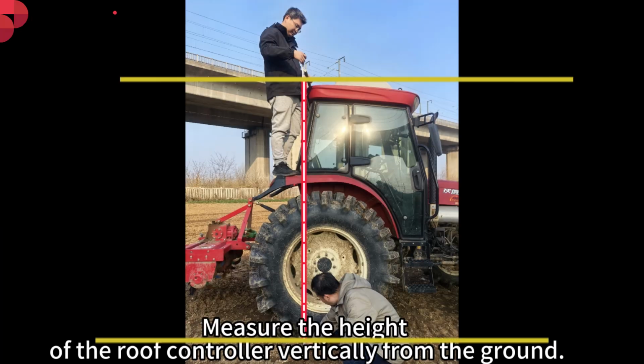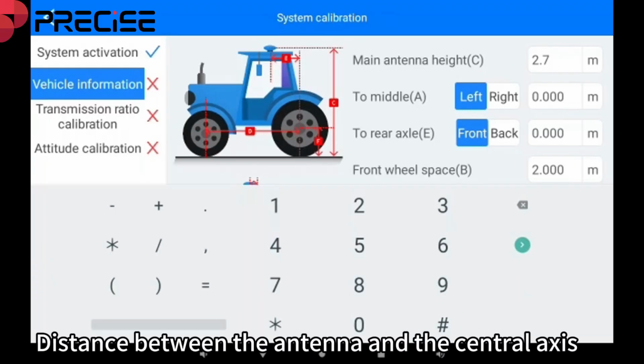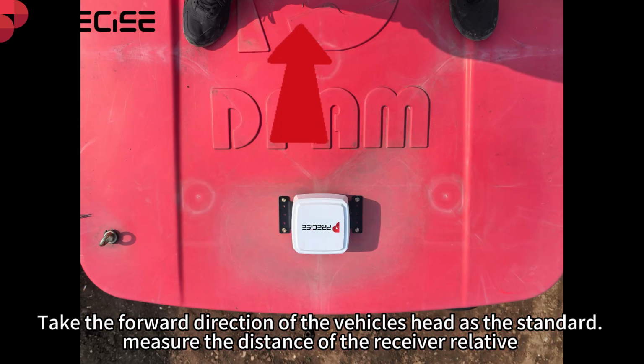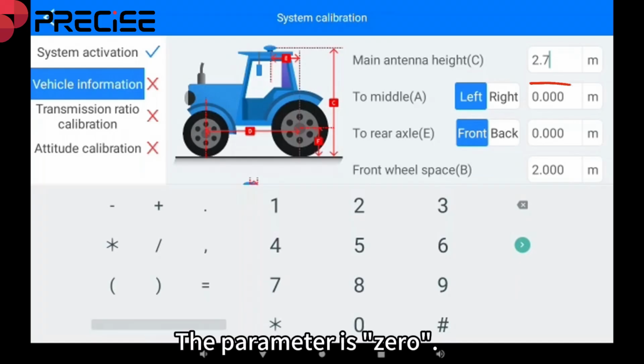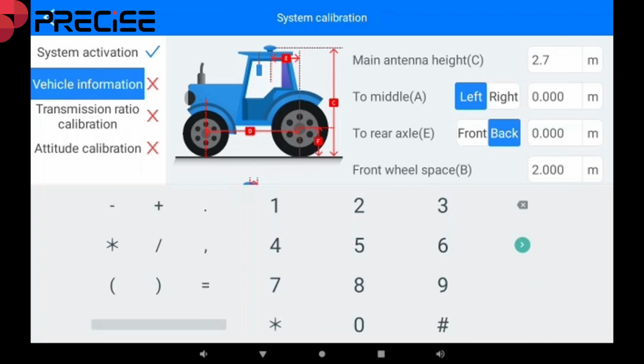Antenna height. Measure the height of the roof controller vertically from the ground and make good marks. Distance between the antenna and the central axis. Take the forward direction of the vehicle's head as the standard measure. The distance of the receiver relative to the central axis of the vehicle. When the receiver is installed on the central axis, the parameter is 0. The position of the antenna on the central axis is defaulted to left.